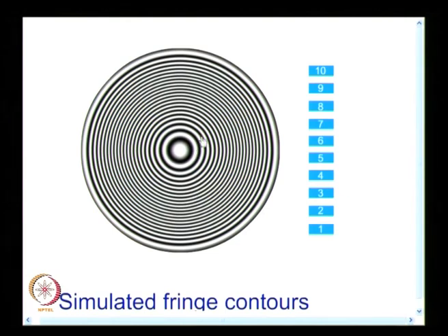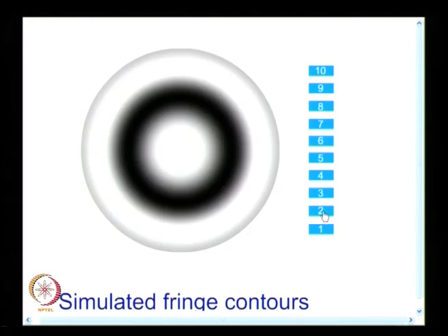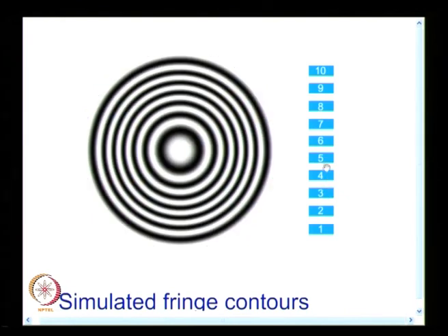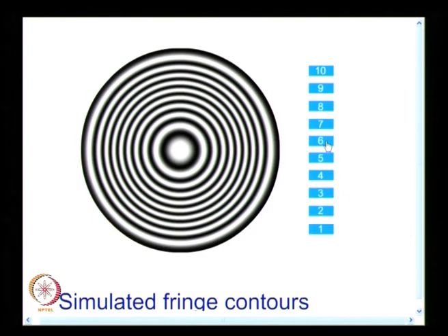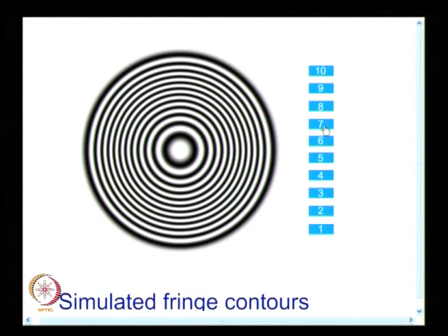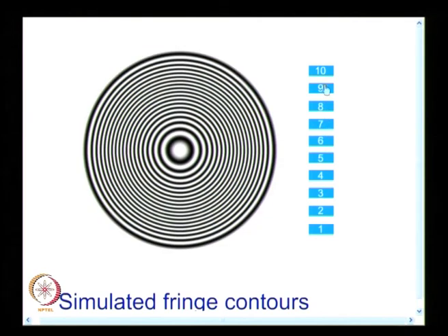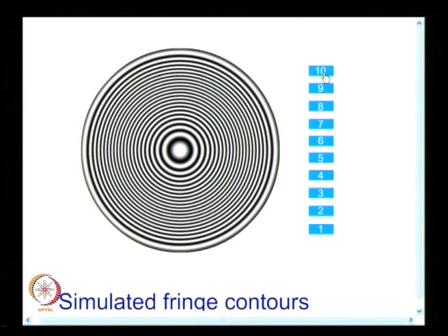In the case of a beam under bending, you saw horizontal lines. In the case of a clamped circular plate, you see beautiful circles, and this is again a function of load applied. So you have concentric circles, and as the load is increased, you have more and more circles.